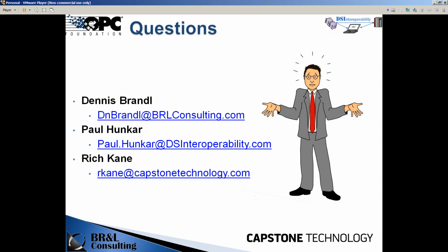Yeah, that's what we expect from people, is that the 95 spec is an abstract spec. It defines equipment and physical assets. The UA implementation of it is also abstract. We expect vendors and end users to define their own instances, their own classes that create the individual pieces of equipment, but it's a framework from which to build that equipment so that they have a standard way of exchanging data and a way of showing relationships.